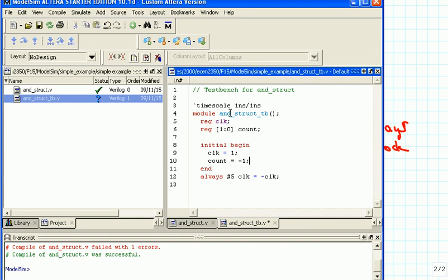And then we use another always block. So that's another one of those procedural blocks. And that is going to be sensitized to the clock, and in particular to the positive edge of the clock. Okay, so we indicate that by saying posedge clock. It's also possible to do negedge clock, but we basically want the counter to react not on the level of the clock signal, but on the transition of the clock signal.